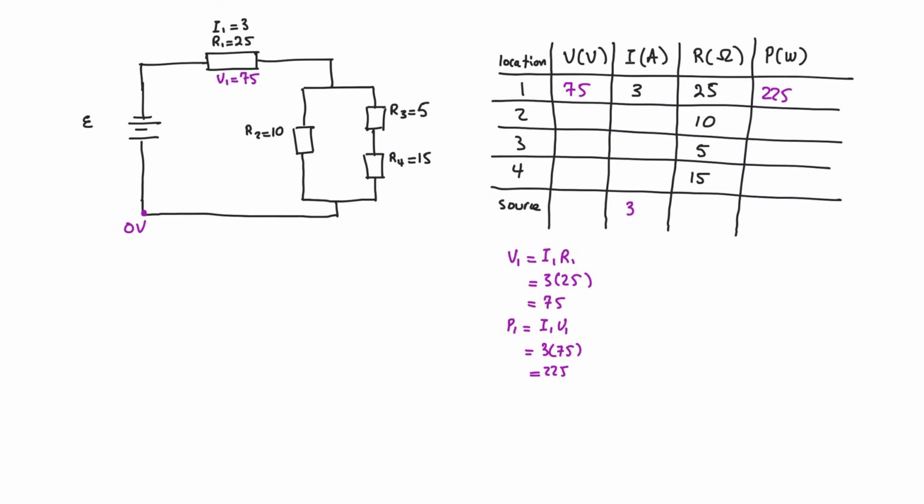Next, I'm going to write all the equations that I can based on Kirchhoff's voltage law and the current law. So to start with Kirchhoff's voltage, I'm going to divide this into 2 loops. One loop is here, so loop 1. That's one path that the charges, or an electron, can take. An electron can come through the battery source, go here, and it can choose this path, which is through resistor 2, and go back. And the other loop, which is going to be loop 2, is when it's going to go through this path. And I will label that with a different color.